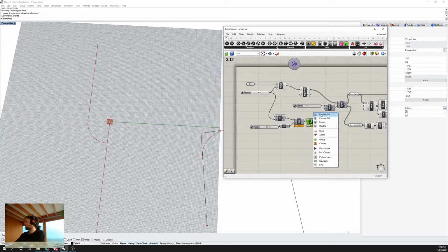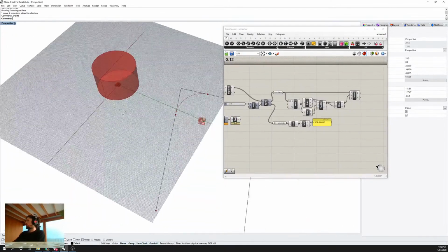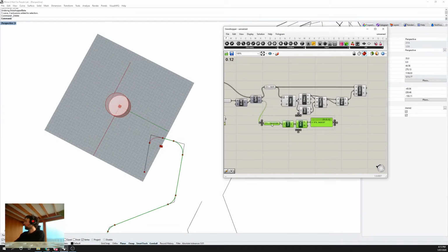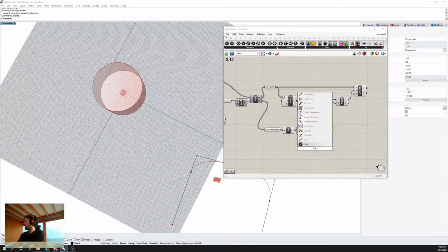So we can turn our bend preview back on for a sec. So we're trying to show our stock material, the remainder of the length of rod before the bend. We know how long this is. We know where we want to draw the stock material from. So I'm going to make a line SDL.